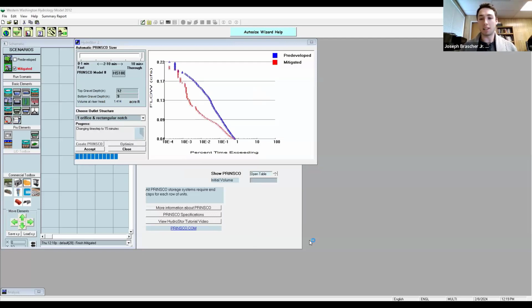So someone asked, do the different pervious surface options have different runoff coefficients associated with them? The pervious surface is not really a runoff coefficient in a single event way of thinking. I could open up the table, but I can't open it while this is running. There are different PERLND values for these different soil types, which actually determine how the hydrologic cycle interacts with each soil type. So it's not even broken down to as simple as a runoff coefficient. It's much more complex than that.